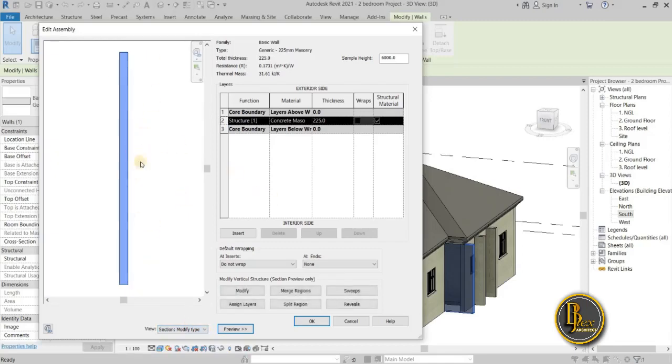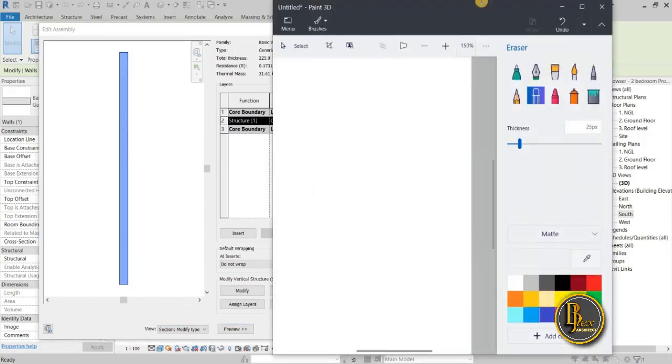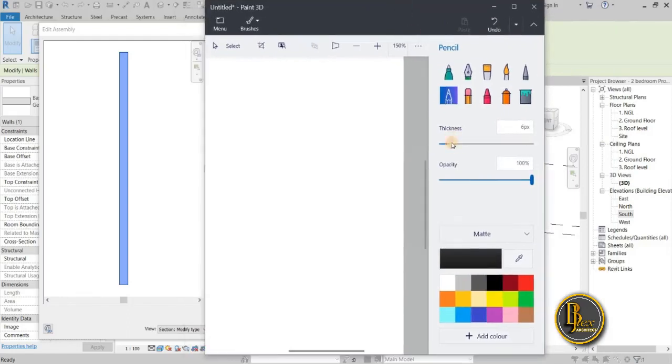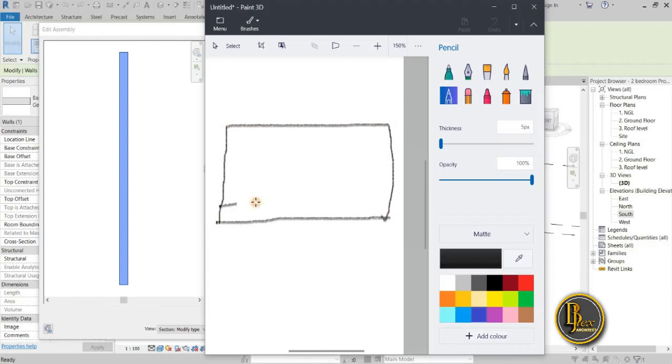So what we are doing now is, let me show you something. Let's say this is the base of our building, this is the main building itself, then we have our DPC level somewhere here. You know, our windows have a sill height of 900. If you remember, the sill height of 900 from this point to the DPC level is 900 millimeters, and from here down to your natural ground level is about 450 millimeters.